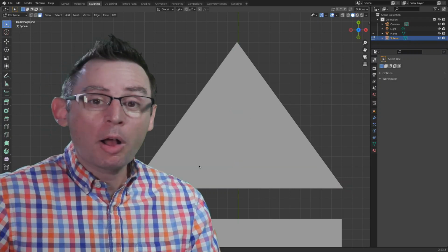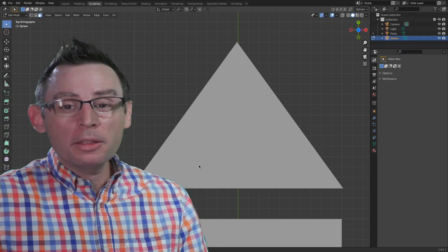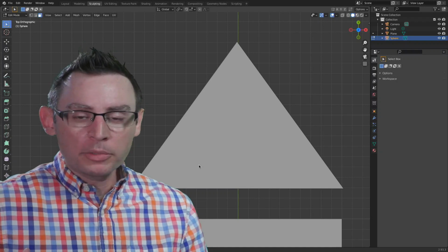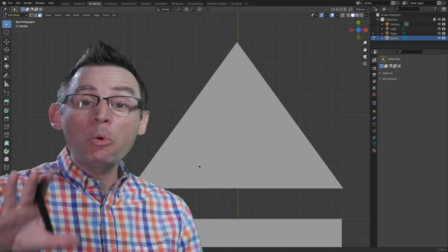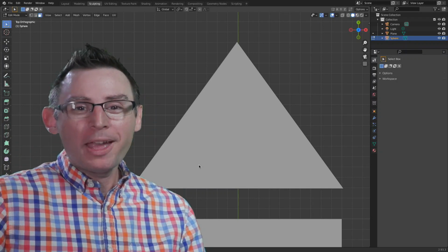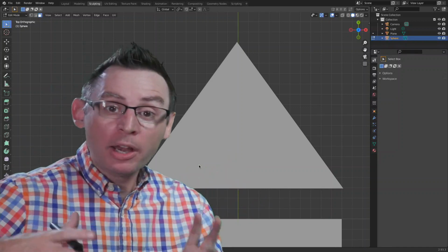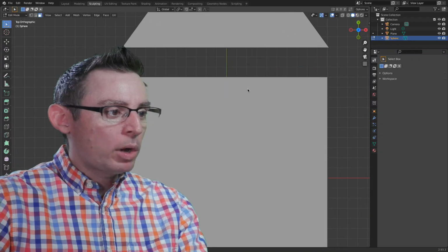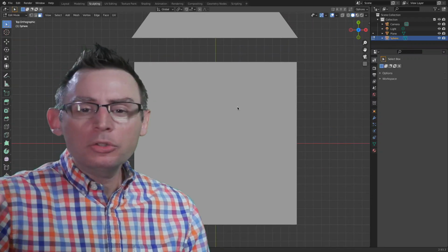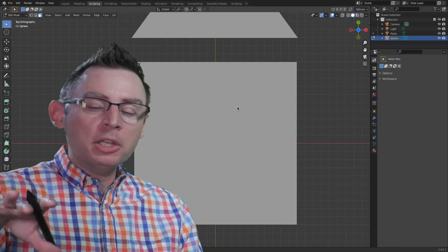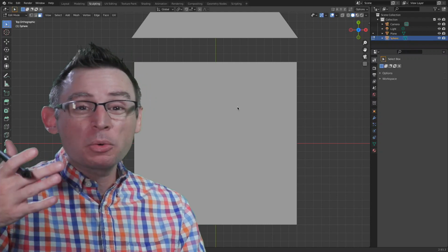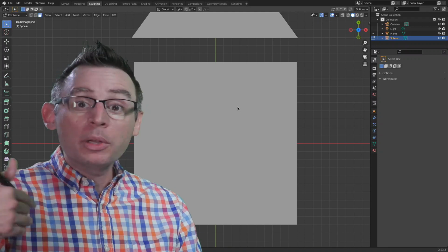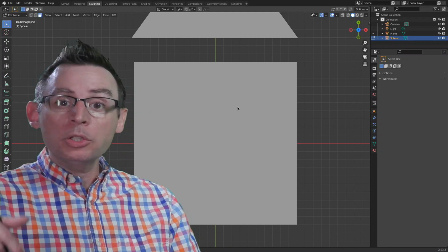Triangles produce a lot of problems for us. They're not really the best surface type. Quad polygons solve all of those problems that we were talking about before and give us the most flexible workflow. Our entire industry and our entire work environment is built around the creation of quad polygons. Triangles are going to happen. Triangles are going to sneak into our models. They're not the worst thing that we can have. They just don't give us as many choices. If we can eliminate a triangle inside of our model, we should look to do so.